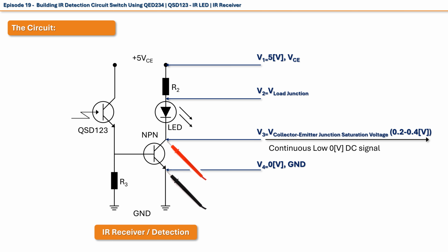Their potentials change with the change of state of the transistor. No matter if the transistor is in cutoff, active, or saturation mode of work, we always take the output signal at the collector junction, if there is a load above. When our NPN transistor is in saturation mode, this junction will have the saturation voltage, in reference to ground.